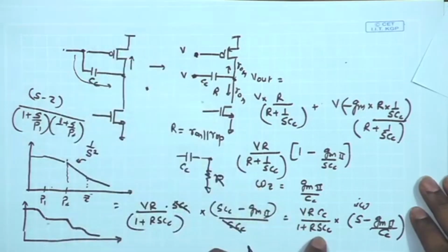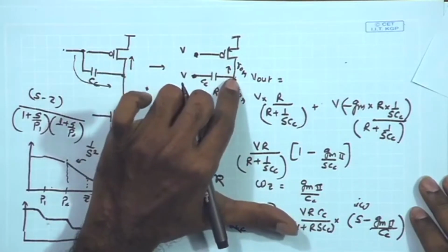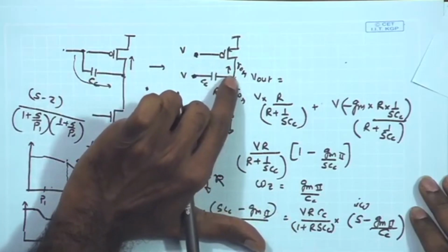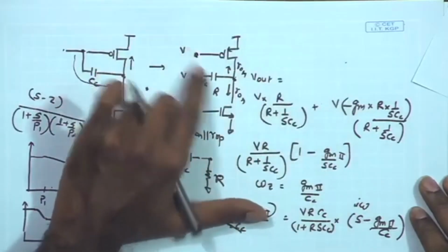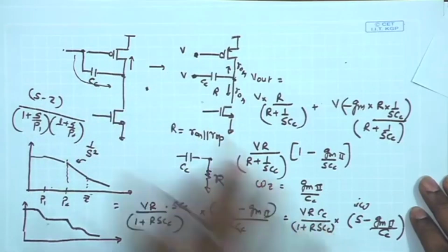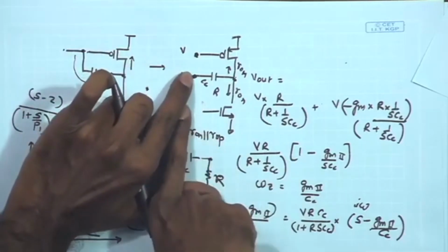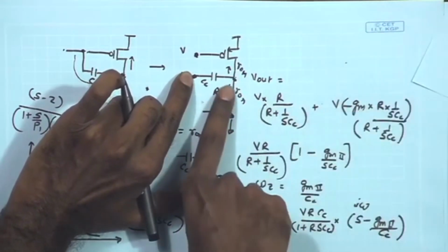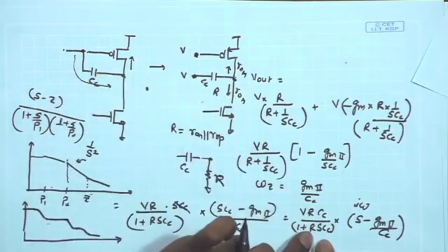And if I look at the other expressions which are coming because of the poles at the two nodes over here and here. So, we have the pole because of the second node going to much higher frequency because of the reducing impedance of CC. So, that term has not been taken care over here. So, here we are ignoring the other circuit combinations, because you have a high impedance node coming over here, and following our arguments in the earlier discussion, we analyzed that this impedance is going to go lower. Here that assumption has not been taken.